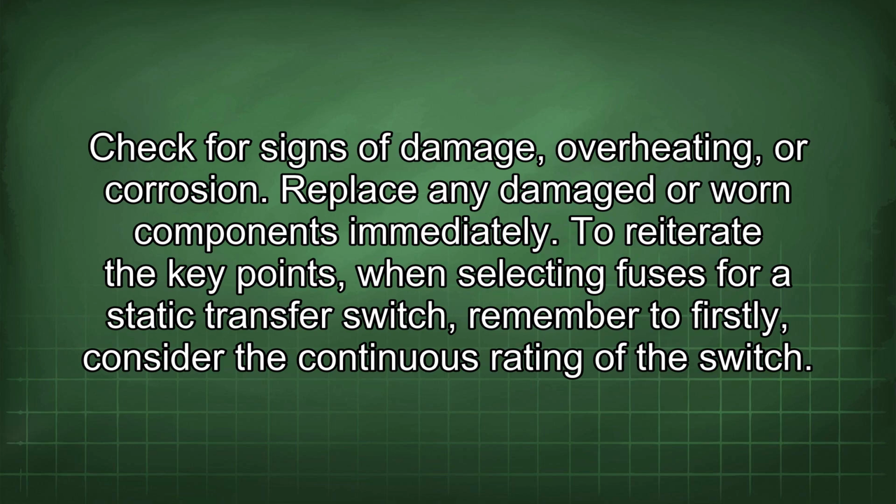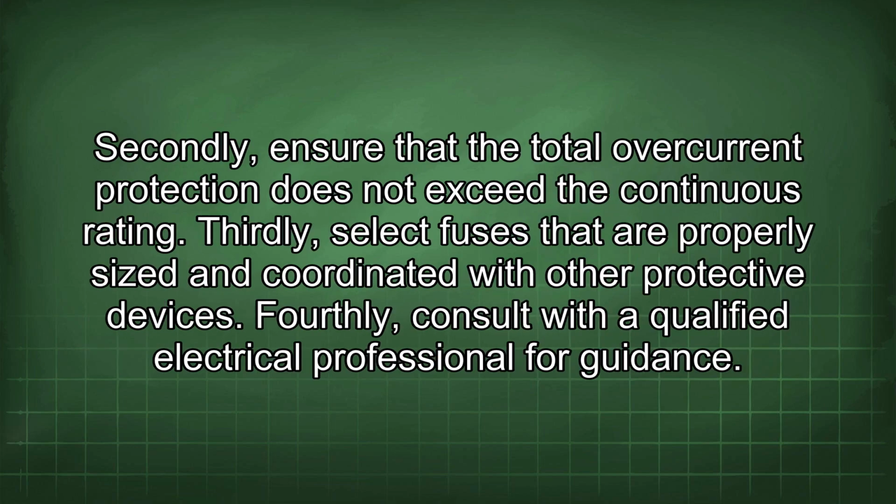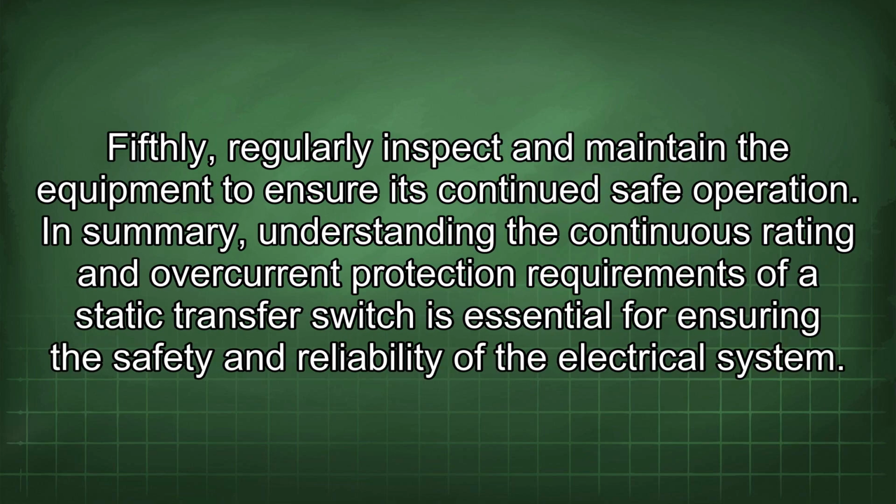To reiterate the key points, when selecting fuses for a static transfer switch, remember to firstly consider the continuous rating of the switch. Secondly, ensure that the total overcurrent protection does not exceed the continuous rating. Thirdly, select fuses that are properly sized and coordinated with other protective devices. Fourthly, consult with a qualified electrical professional for guidance. Fifthly, regularly inspect and maintain the equipment to ensure its continued safe operation.